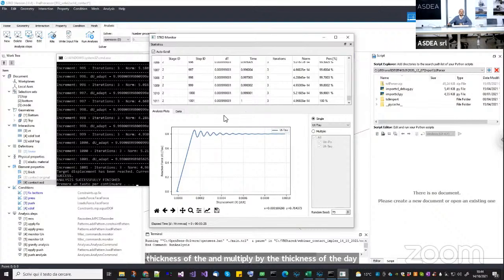So it is not necessary to make it this high. For example, if I keep it only 1 order of magnitude higher than the shear modulus, you will see that those oscillations will be reduced a lot, while the solution is still the same.